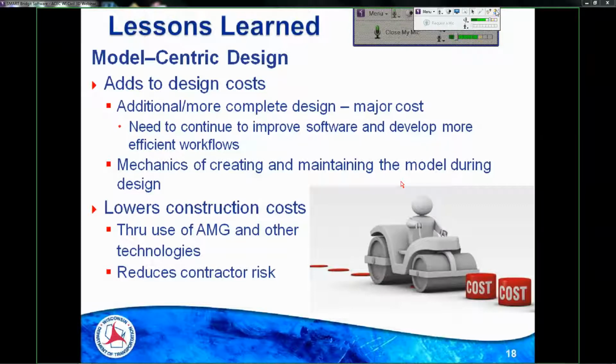Well, I think that the surfaces represent design intent better than a set of 3D line strings that we're calling longitudinal break lines. And when it becomes a contractual document, I think the whole concept is in a better place, because the surface is a very black and white, clean-cut representation of design intent. Longitudinal break lines depend on how you triangulate them, right? So I think we're in a better place with surface model delivery for advancing this and making our design model contractual in construction.